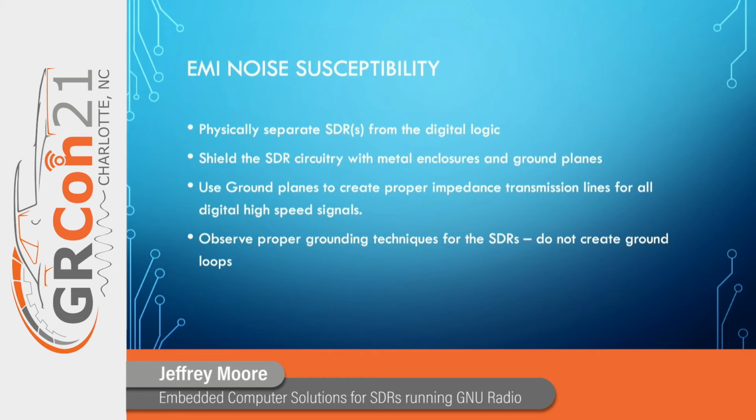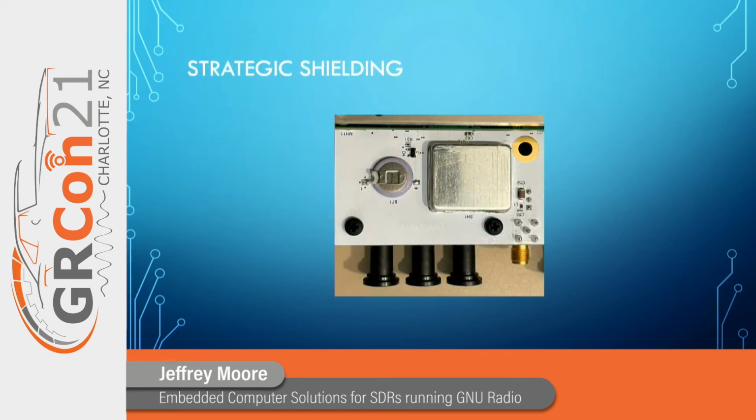And there are certain kinds of chips that are particularly sensitive to EMI generated noise. For example, GPS receivers. And in the next slide, you'll see that. This is a portion of one of those boards that you saw earlier, where there is a shield over one of these u-blox, UBLOX. They're a Swiss brand of GPS and other kinds of radio receiver chips. So there's a u-blox NEO-M8 series GPS chip underneath this shield.